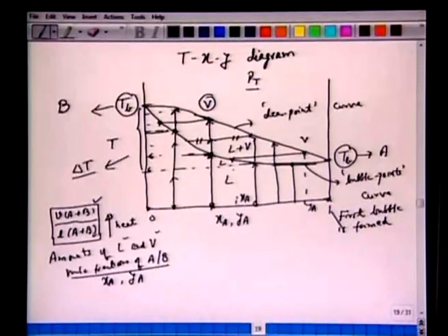We further heat it, there is separation, liquid plus vapor. The vapor phase contains so much mole fraction Ya given by this curve here, and the liquid phase will contain so much mole fraction Xa given by this curve here. If we further heat it, boiling continues till we reach this point, and the entire liquid is converted into vapor phase. This temperature we call the dew point.